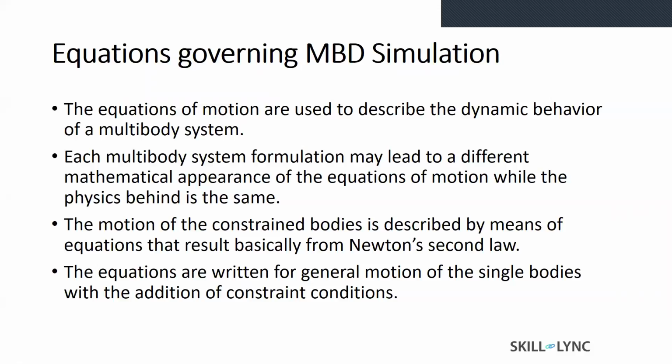That's a solver. What you'll be working on in the graphical user interface is Motion View, which is the pre-processing software, and the solver here will be MotionSolve. When you create a constraint, a joint or a motion, whatever you create on the graphical user interface, it will be written out in terms of equations in the solver. Those equations get solved every time you run the simulation. The key thing I wanted to say here is that everything depends on Newton's second law of motion.